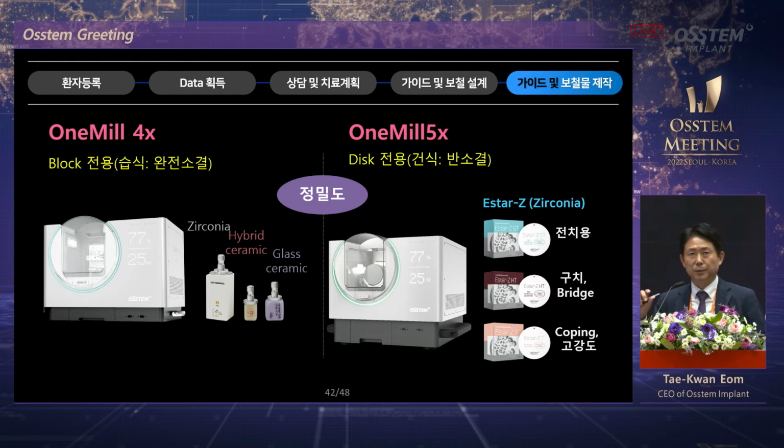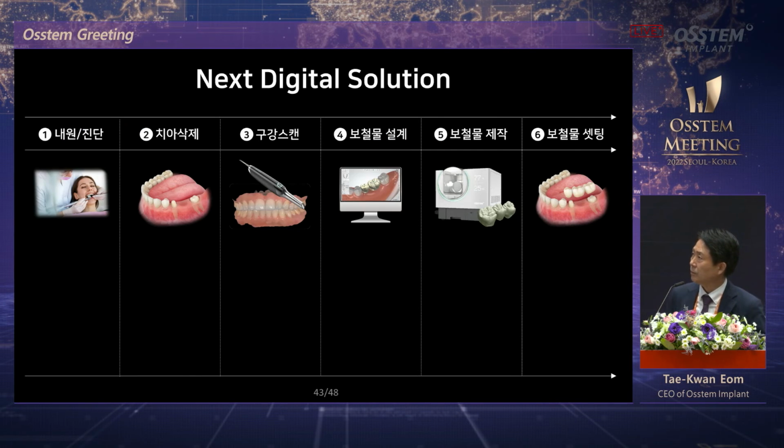there's a motor spindle. So when it is moving, there is a bed, solid bed, because high-speed milling is occurring, so the bed should be solid, not to shake the machine. So we made a cast for the bed, and you will think this is too heavy, but heavy base would contribute to higher precision. So based on our measurements, that is the most precise milling machine.